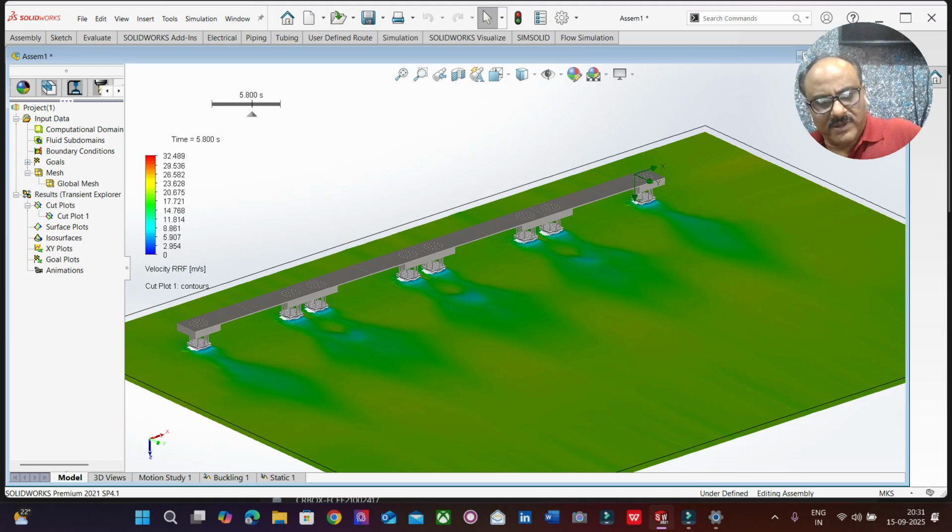The pile is going to have a pile cap, and over the pile cap is what we build a pier, and on the pier we build a pier cap, and the pier cap is the member that is going to hold the superstructure, the bridge deck or the girders. That can be a pre-stressed girder, or a post-stressed girder, or box girders. Many different types of girders are there, depending upon the usage.